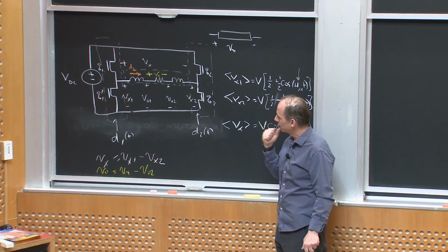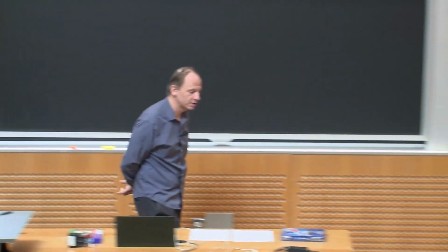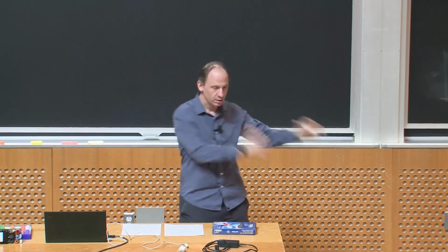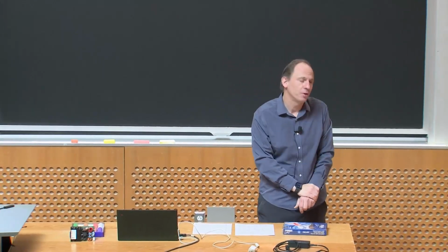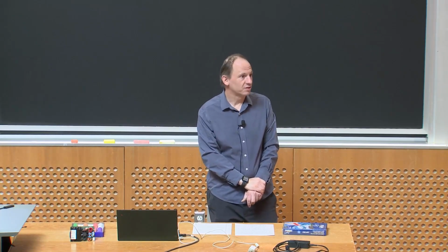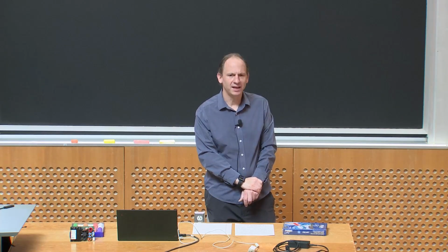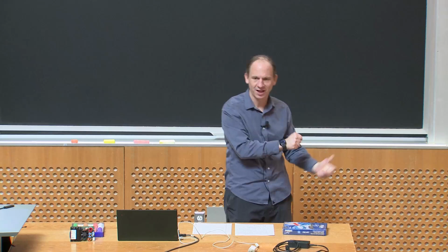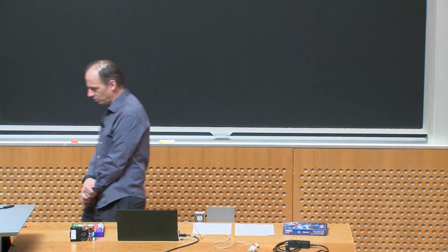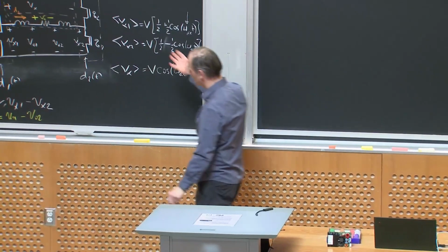But I would like to note that there are some times when I only really want to go one direction. In fact, there's times when I only want to take power from the wall and put it out to the DC side, right? If I'm building a computer power supply, at least in ones today, there's no real reason for me to do anything except absorb power from the AC side and put it to the DC side, right? And if that's the only thing I want to do, I could do that conversion function with this circuit, right?